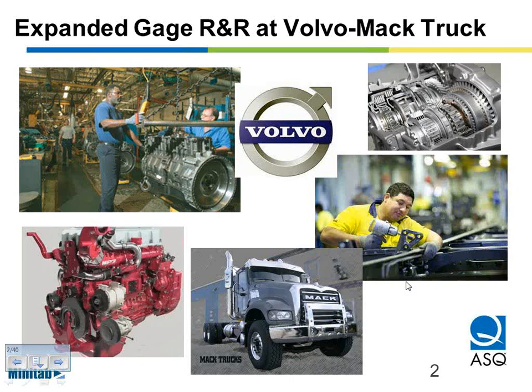What struck me upon hearing that was that that measurement system is going to require an expanded gauge R&R, not your typical gauge R&R that would look at the part and the operator as the two main components of variation, but also, in order to be a complete study and a definitive study, it would have to have what? It would have to have the gauge as another component.